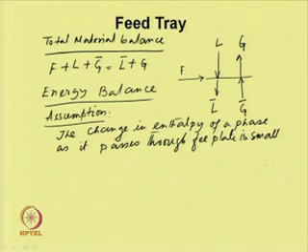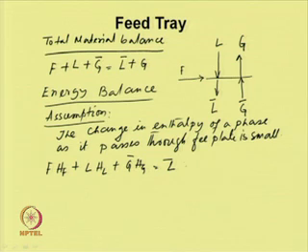If we assume that, then we can write the energy balance equation: F H_F plus L H_L plus G bar H_G is equal to L bar H_L plus G H_G.